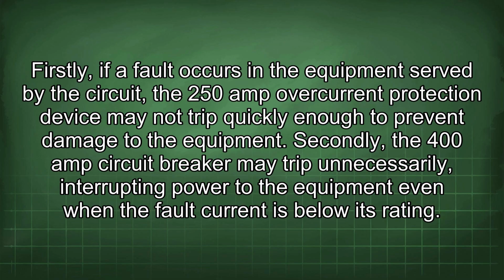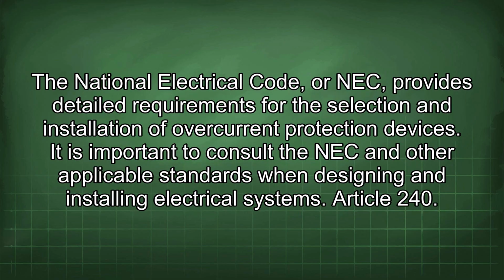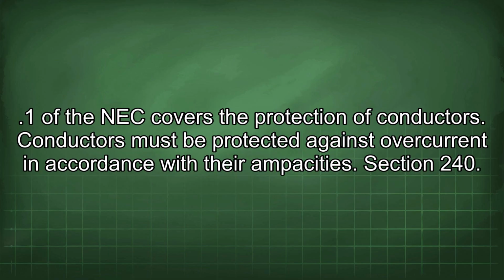The National Electrical Code, or NEC, provides detailed requirements for the selection and installation of overcurrent protection devices. It is important to consult the NEC and other applicable standards when designing and installing electrical systems. Article 240.1 of the NEC covers the protection of conductors. Conductors must be protected against overcurrent in accordance with their ampacities.